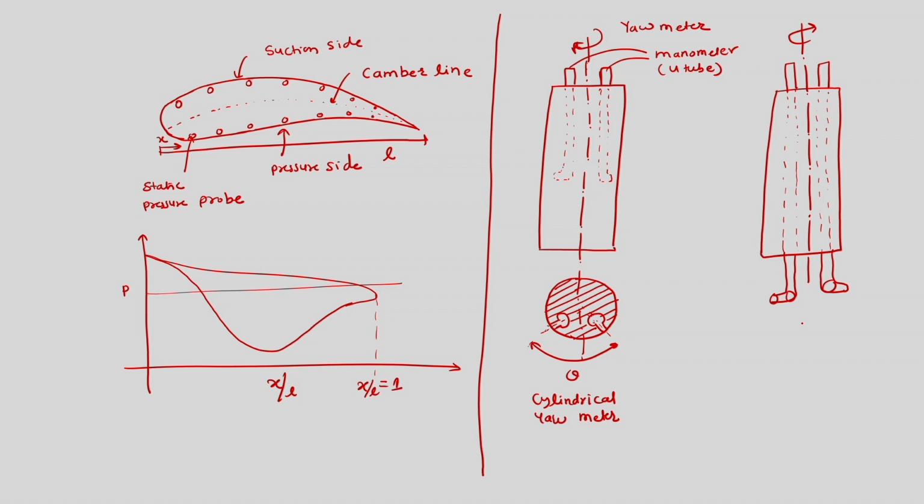And here if we see, we can see that internally there are tubes connected to the manometers, and those tubes when rotated would measure differential pressures in each limb, but when this particular orientation is reached, they will measure the same pressure such that the difference is negligible, and from their orientation we can find out the direction of velocity.